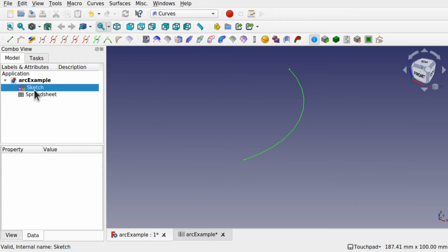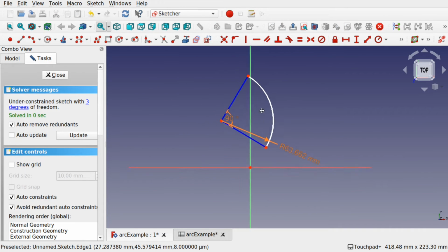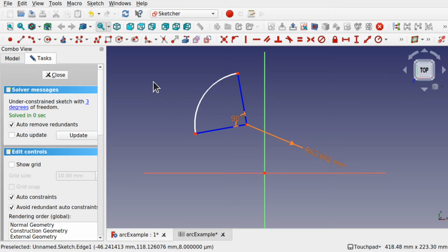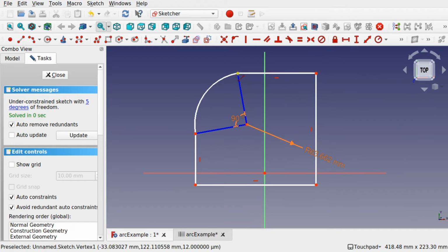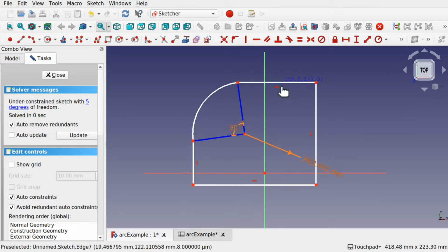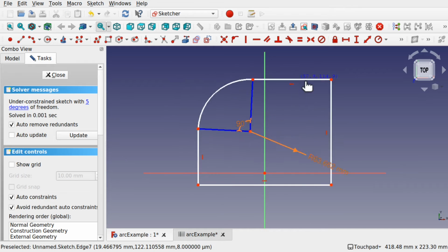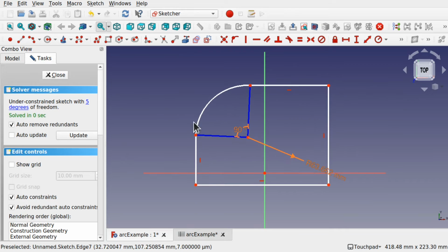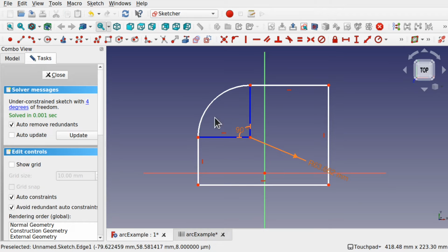One thing to remember is that with the sketch, if we're going to create a closed sketch, then we may need to leave some of the geometry unconstrained. So let's place, say, a line in here, connect that down here, line across, and we'll connect up to the top. So now we've got a dynamic sketch. You can see they're changing. And say if I wanted to keep this horizontal, I can put a horizontal constraint in here, that'll keep that horizontal.